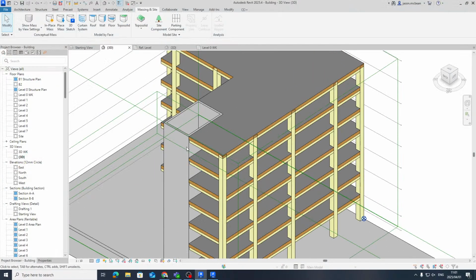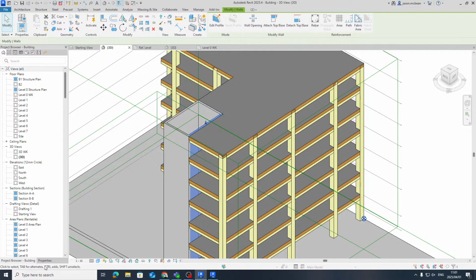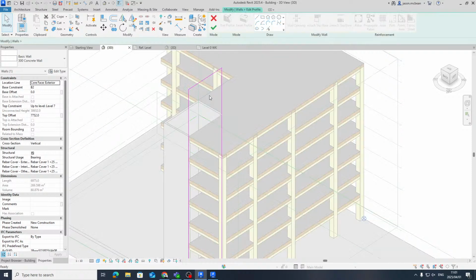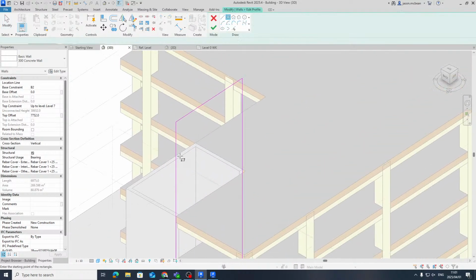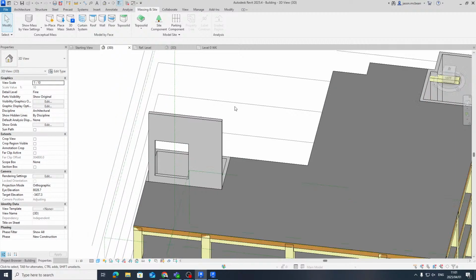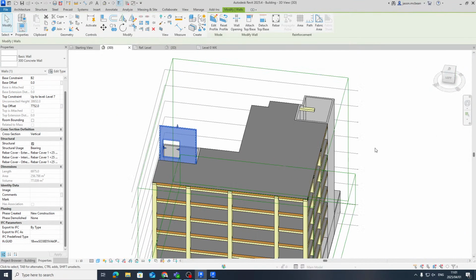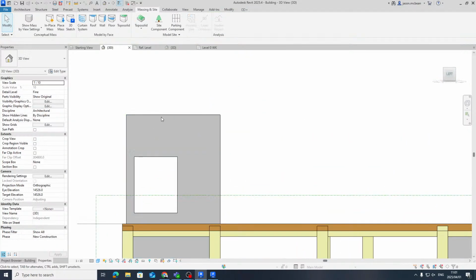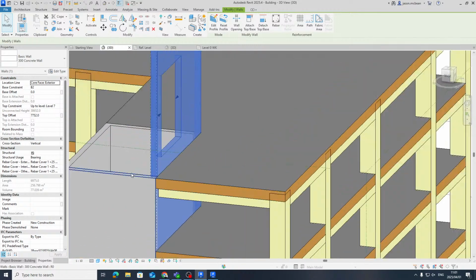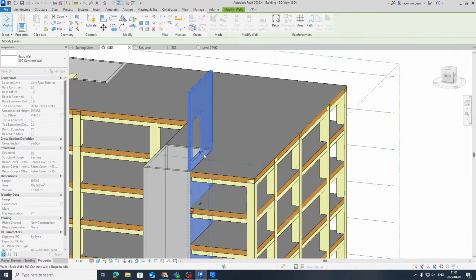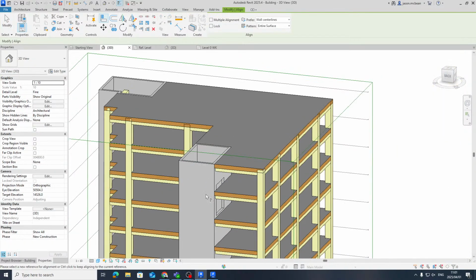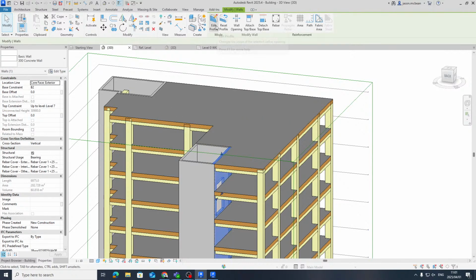But now in Revit, if I want to do the same thing, it gets complicated because now you've got to understand levels. You can push and pull these things up. You can go and edit profiles, but it's not the same. Okay, it's not as intuitive. It's a lot more difficult to get used to. You can't just make open shapes. Okay, so this is all driven by levels, and you're constantly having to work with levels. Same thing with ArchiCAD. This gets a lot more difficult to use, and then walls won't join correctly. So if you pull this down, for example, yeah, things just don't work as well, unless you know what you're doing. This is very complicated to get used to in the beginning.